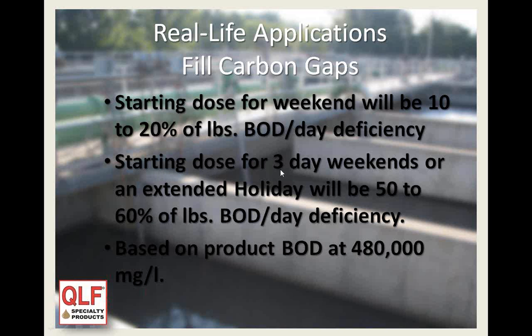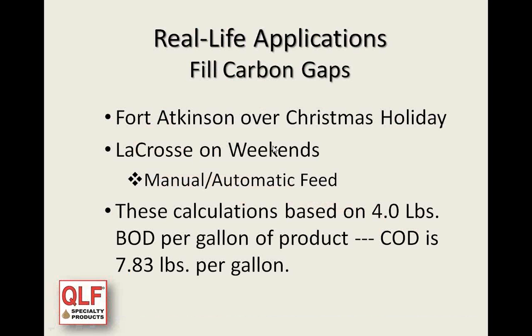If your gap is going to be 3 days or longer, like an extended holiday, then we look at about a 50 to 60% dose rate, based on the product being at a 480 milligram per liter BOD level. We've done Fort Atkinson.